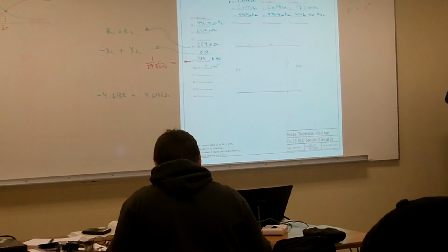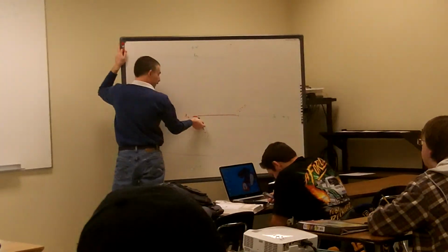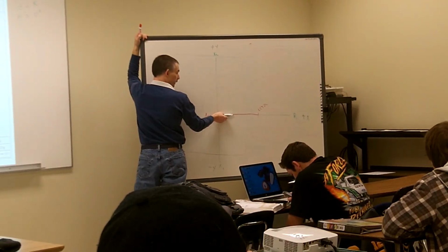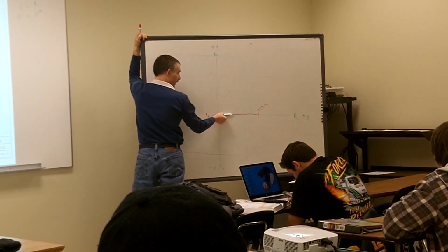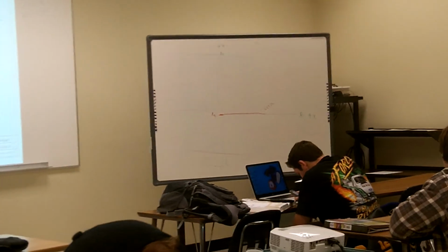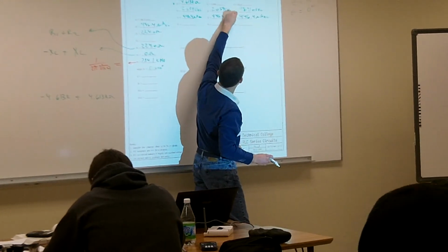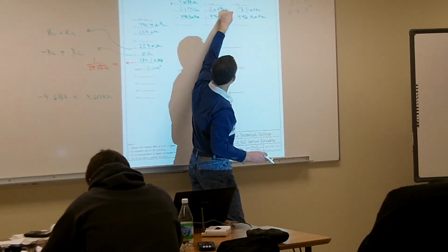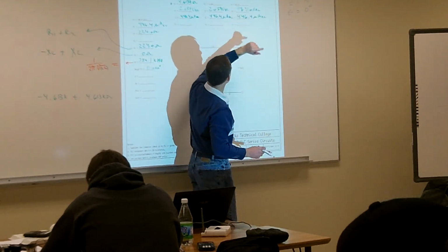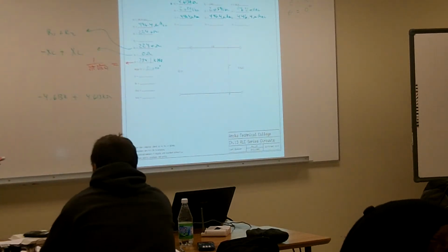And again, we can use this as either voltage or impedance. It doesn't really matter. But my total source voltage is always going to ride approximately the same place as it does on my impedance angle. It's going to be right here. So my source voltage is always going to equal my VR. So in an ideal circuit, my voltage across my resistor, after these 2 get canceled out, should end up equaling my source voltage, but it doesn't. Why is that? Do you know where the other 2 millivolts go?